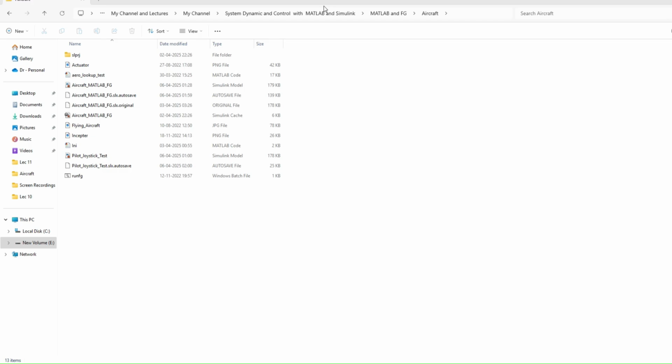Here I would like to mention one very important point. For the present case, I am considering the F-18 model, and the related files I have downloaded and put in the FlightGear folder, and so many other aircraft are already there in the FlightGear folder. But if you want to design your own UAV aircraft and see the simulation and visualization, you can design it, for example, in SolidWorks, import the SolidWorks file in the AC3D software, put all the textures, and then put the AC3D file in the FlightGear folders, in a model.